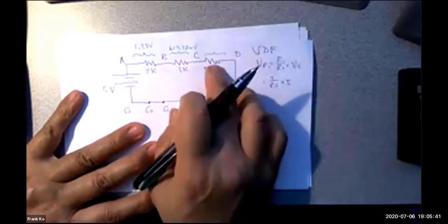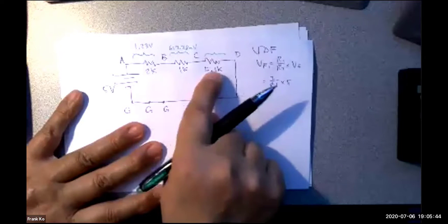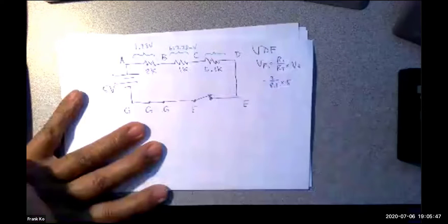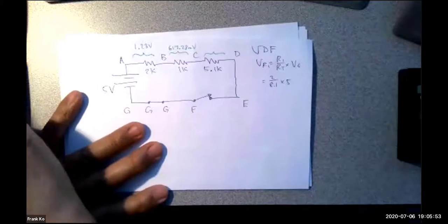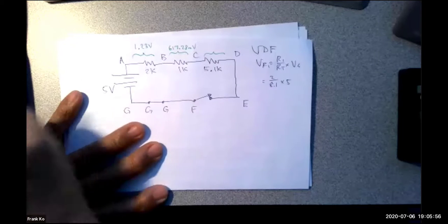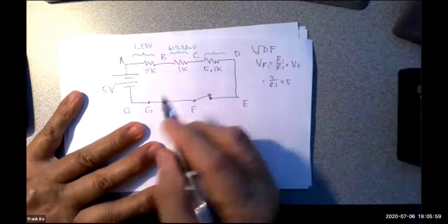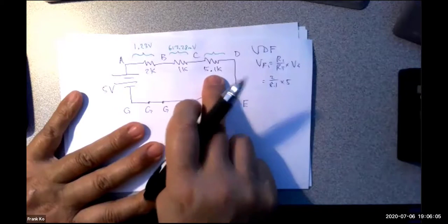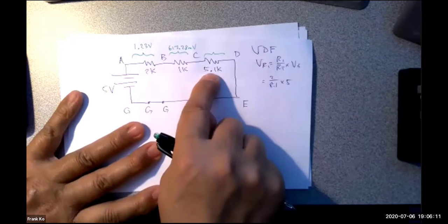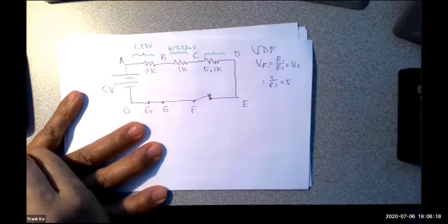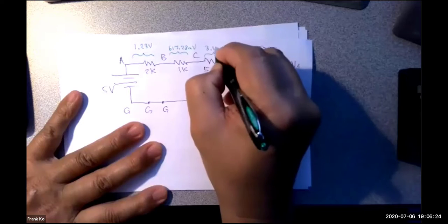All right. And now we're going to do the last one, which is nothing more than 5.1 divided by 8.1 times 5. And this question will go to Dana. 5.1 divided by 8.1 times 5. What's our last voltage? I'm sorry, what? Can you repeat the question? Well, we're calculating VR3 in this particular example, using the voltage divider formula. So I said it would be 5.1 divided by 8.1 times 5. And your magic calculator spits out 3.15 volts. Perfect. Everybody okay with those numbers?